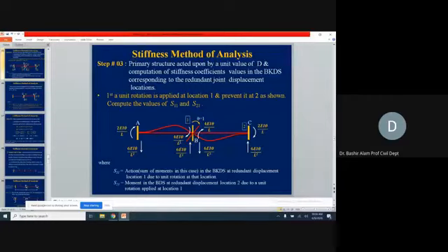This is the total unbalanced moment. If we divide this by the distance between the couple, that will give the magnitude of these reactions. So 6EI theta divided by L square, L multiplied by L becoming L square. This is how we get the balancing couple, 6EI theta divided by L square.